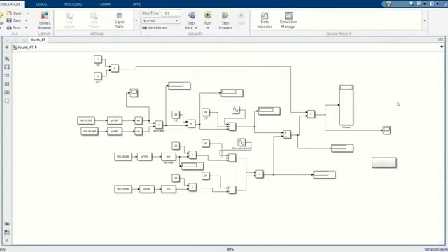We have also developed the model of tower shadow effect with certain blocks. As you can see, VH is hub height wind speed, A is the azimuthal angle that we have squared. After that, we have taken the range of azimuth angle theta from 100 to 260 with a difference of 20, multiplied by pi by 180 and given to sine square.